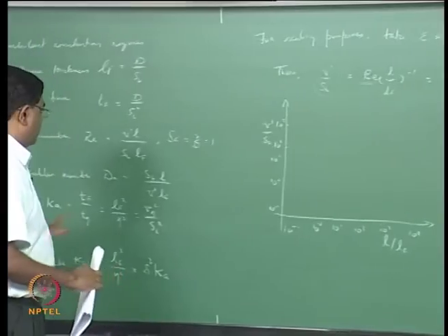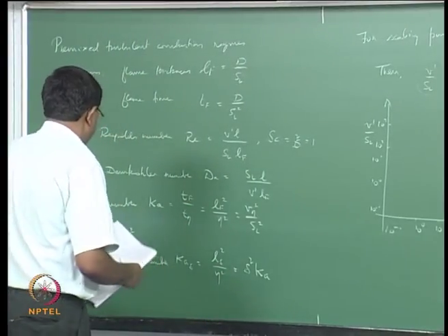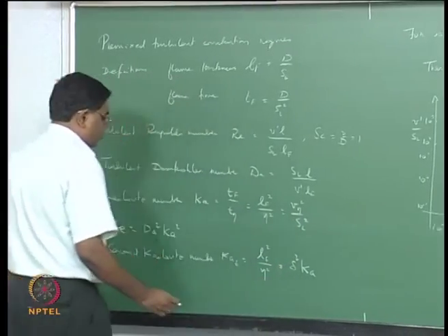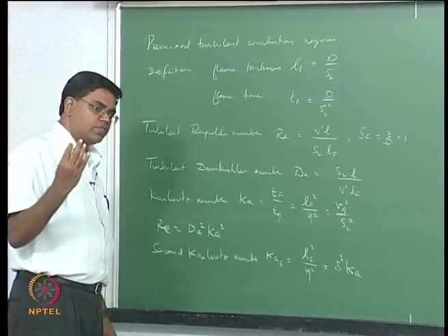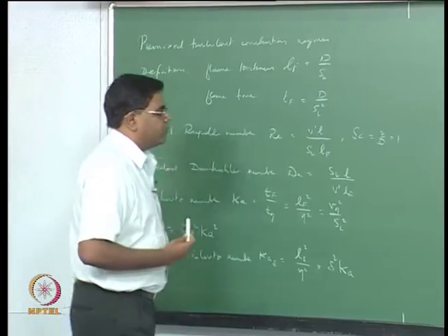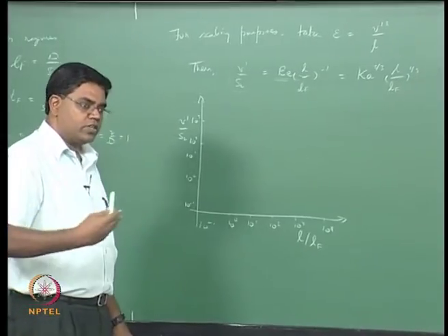In this particular exercise, this involves the Zeldovich scaling, and we're using a Zeldovich number value of about 10, something we saw long ago when we were scaling the premixed flame thickness to find out how thick the reaction zone is relative to the preheat zone.